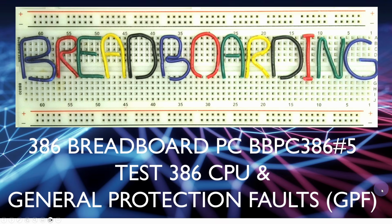So this is video number 5 of the 386 Breadboard PC series, and in this video we're going to be testing the 386 CPU with our no operation code instructions. And in fact it turns out that there's a problem with using this. We end up generating something called a general protection fault, so we'll be going into the background of this and finding better ways of testing the CPU.